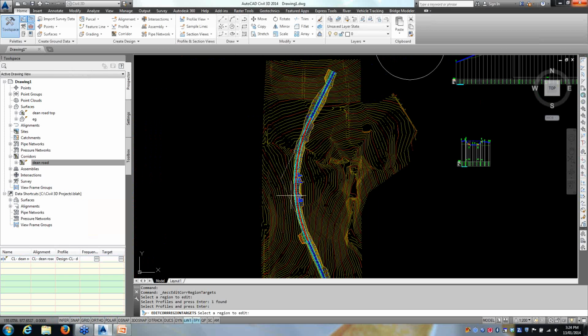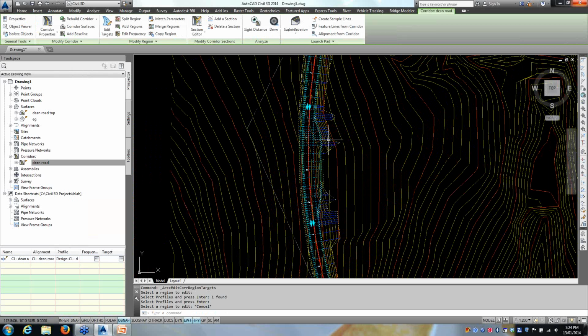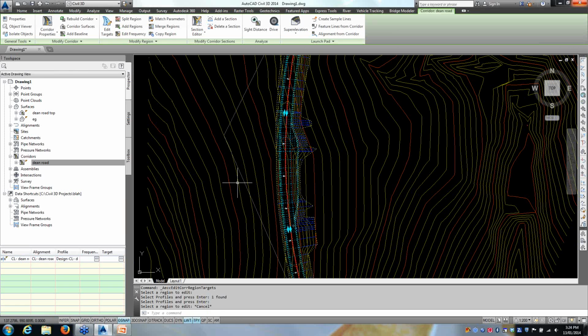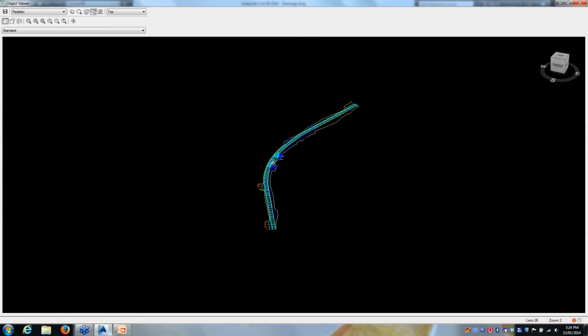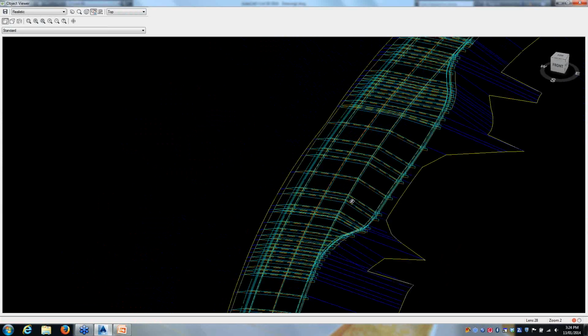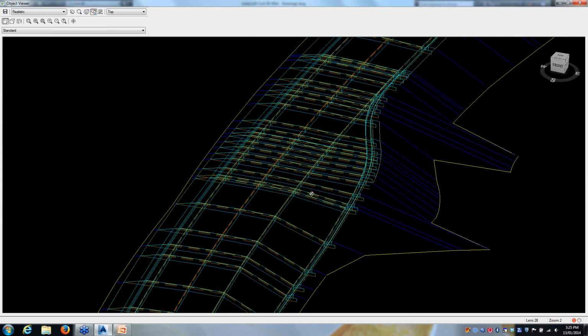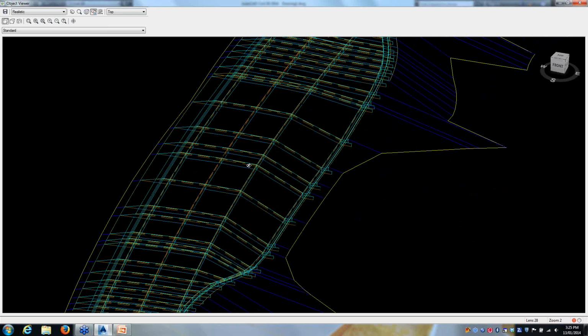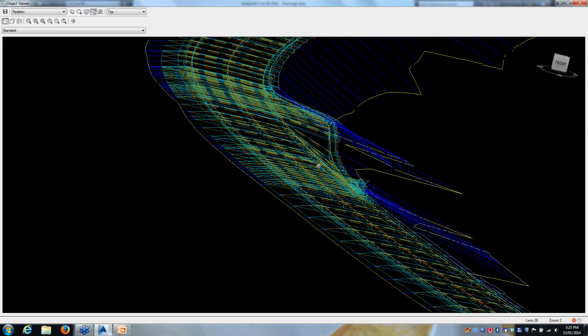And now we should see there's a major change in the batter slopes there, which is what you'd expect. Check it out in the object viewer. This will be fairly extreme. There we go. You can see what's happened to the crossfall. We've got our 2% crossfall here, but in the bus bay it's done our dramatic change in there, so you can definitely see that it's happening. Get a big twist in the side of it. So we've widened out to the alignment and then changed its elevation to match that drastic profile that we've drawn.